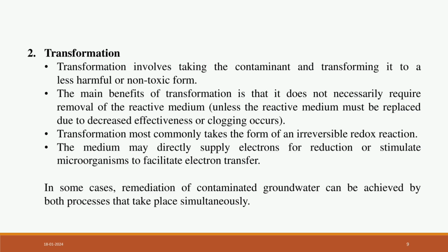The main benefit of transformation is that it does not necessarily require removal of the reactive medium, unless the reactive medium must be replaced due to decreased effectiveness or clogging. Transformation most commonly takes the form of an irreversible redox reaction. The medium may directly supply electrons for reduction or stimulate microorganisms to facilitate electron transfer. In some cases, remediation of contaminated groundwater can be achieved by both processes taking place simultaneously. Moving to the next slide.